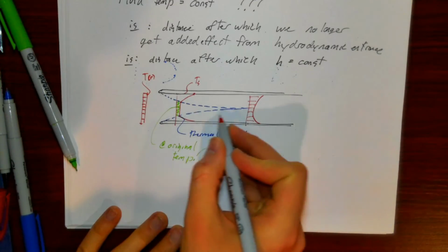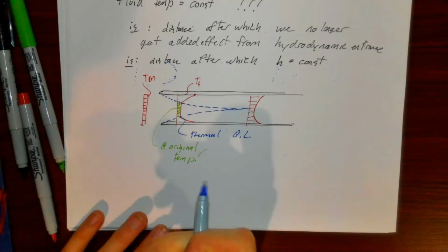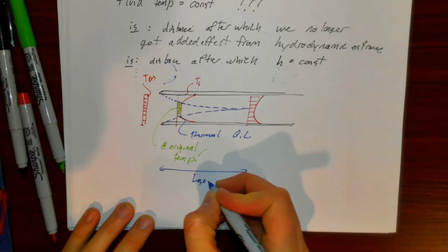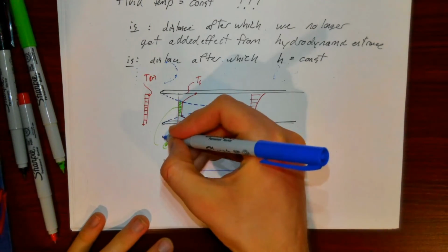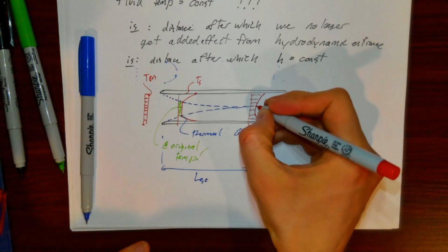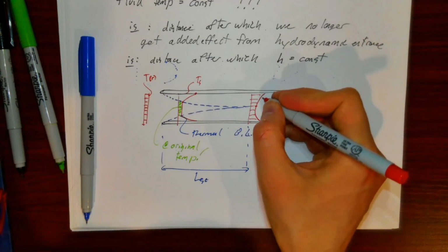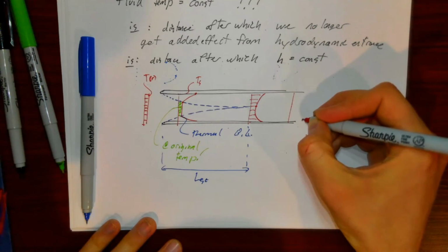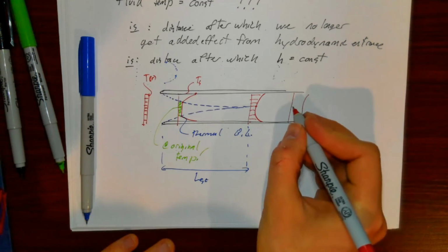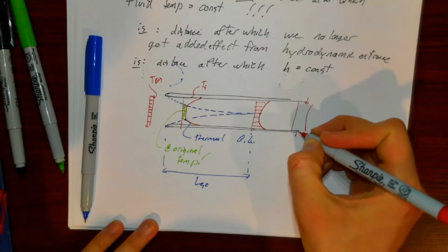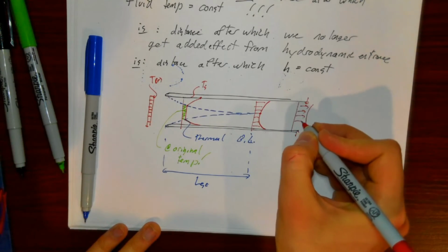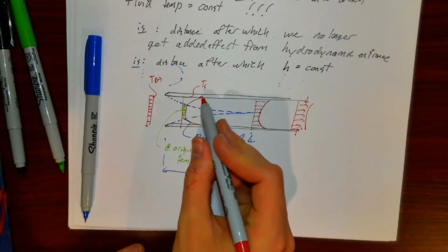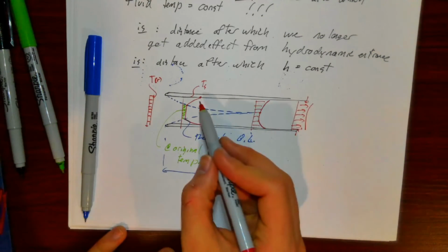It's just finally when you're past your thermal entrance length, the fluid at the middle at least has had some effect from your temperature from your edge. And then later on, you still have some deviation, right? You still have heat flowing in from the outside. It's just that every part of the fluid is now somewhat affected by your edge temperature, something like that, right?